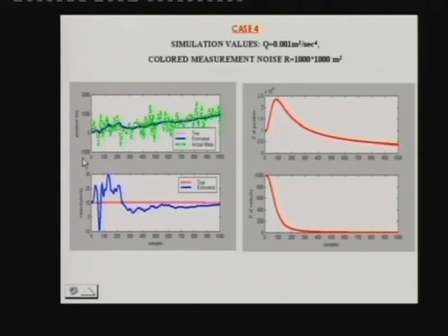See, this scale is significantly higher, again the cursor is gone, this scale is significantly higher, this is 0, this is minus 1000 and the top one is plus 1000, previously it was 200, 400, 600. So the scale is much higher. Whenever the average value of noise is going up, it is going positive, whenever it will go down, it will go negative. See, here the average value of noise is significantly positive, can you see that, the green lines? If you take an average within that interval, it will become significantly positive and the estimate is going up, right, plus there is correlation. So the estimate is trying to track the noise DC, I mean low frequency components.